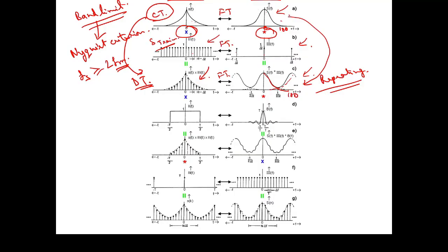So frequency components above this FM would also be present. So to make our system capable of handling whatever the signal component you are trying to analyze, we have to band limit the signal such that this Nyquist criteria is being followed. Okay, the Nyquist criteria is being followed.